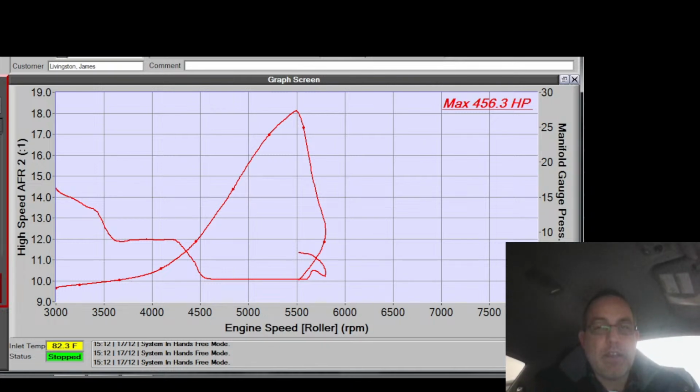What cams are in this? It's got B's, right? And that's somewhat different, but it ain't that much different. Which is a great cam. I like it. I'm just trying to figure out why the tip-in is so much. When I tip in, it goes stupid rich. And I'm trying to figure out why it gets so rich.